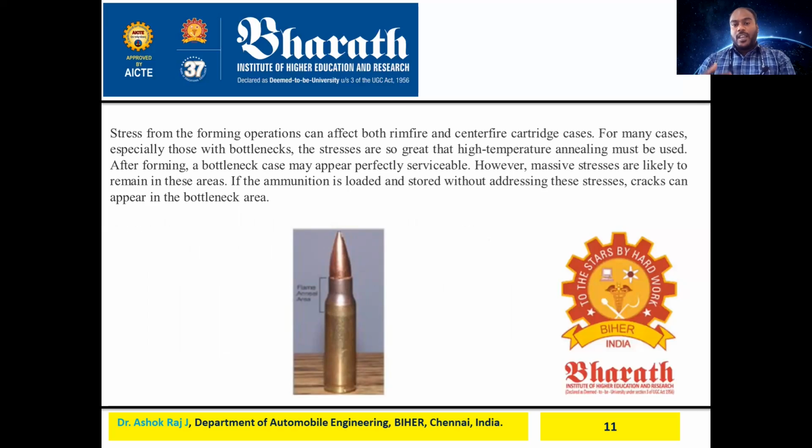After forming, a bottleneck case may appear perfectly serviceable, but massive stresses are likely to remain in those areas. If ammunition is loaded and stored without addressing those stresses, cracks can appear in the bottleneck area. You can see this.